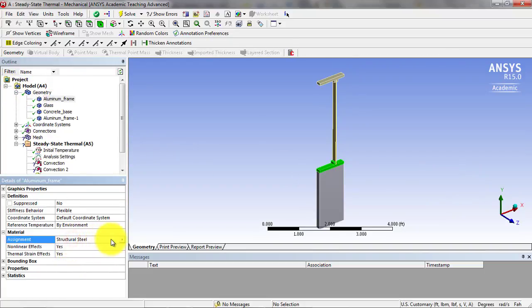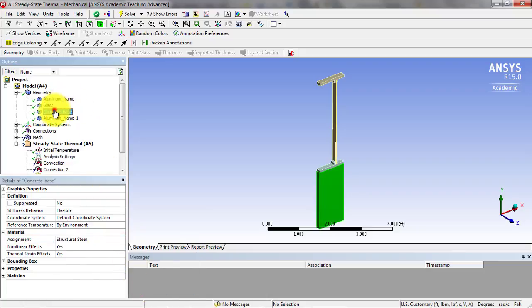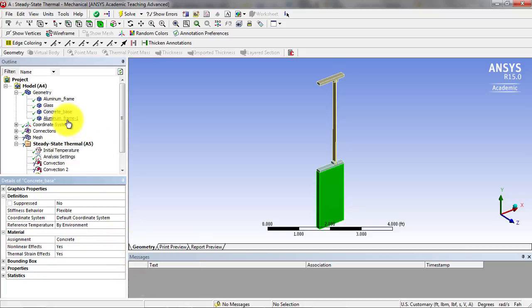Oh, so it resets. So I think the problem that we have here is with step files, you don't maintain the things, the properties, the geometry, applying the materials. We're going to find the boundary conditions got lost, and the mesh is basically reset. So all that kind of goes away when we do use the step file. So ideally, you can use the SolidWorks integration, but if you don't have it, you just have to go with what you got.